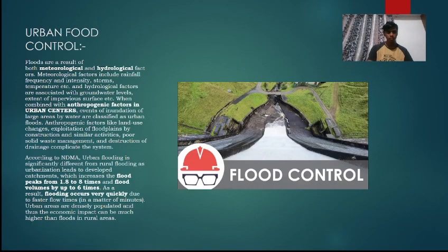The last topic is urban flood control. Floods are a result of both meteorological and hydrological factors: frequency and intensity of storms associated with groundwater levels and the extent of impervious surfaces. When combined with anthropogenic factors in urban centers, the events and inundations intensify. Anthropogenic factors lead to changes in floodplains through construction and similar activities, poor solid waste management, and destruction of the drainage system. According to NDMA, urban flooding is significantly different from rural flooding.